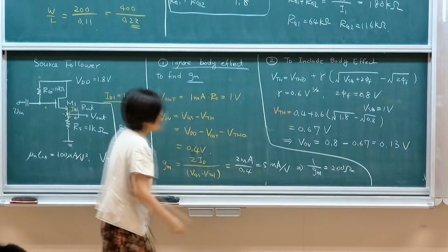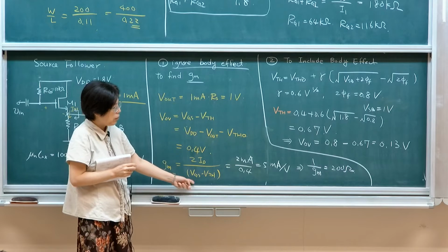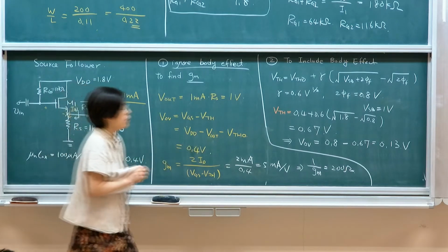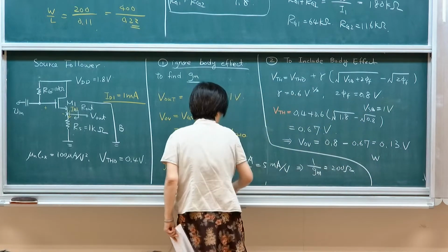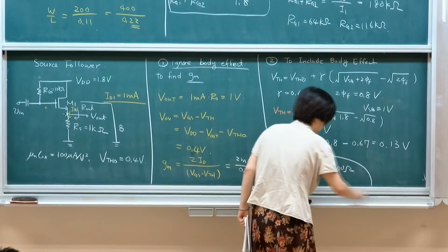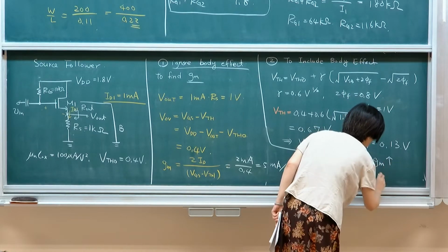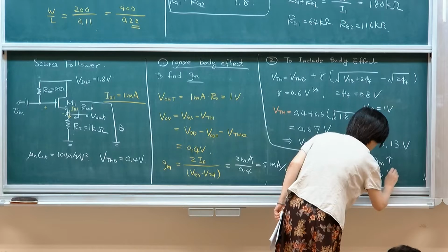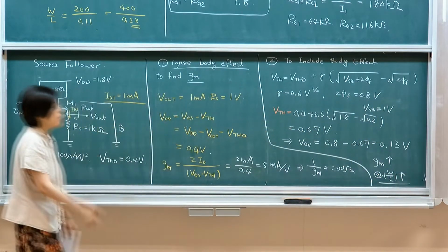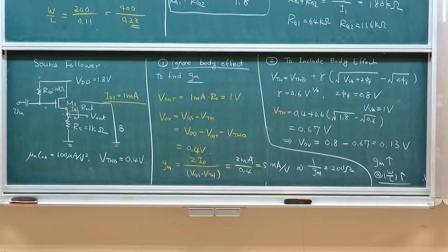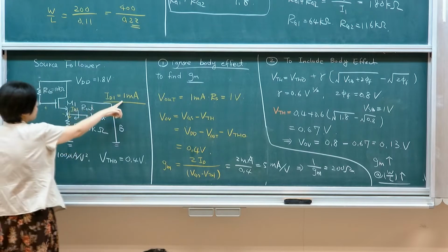So based on this circuit, you would then have a much smaller overdrive at the bottom. So 1 over gm will be higher. I should say gm will increase at the cost of increased W over L. The reason why we don't see this is that we didn't go back to check under this balancing point, this 1 milliamp.